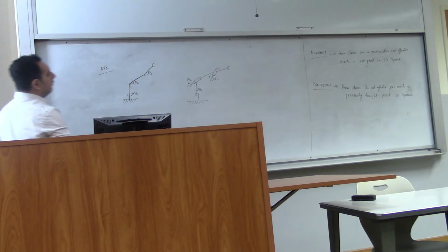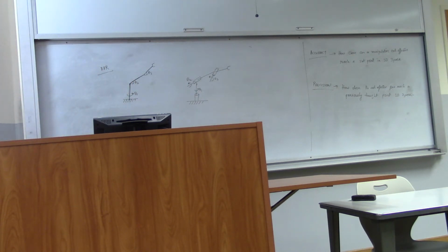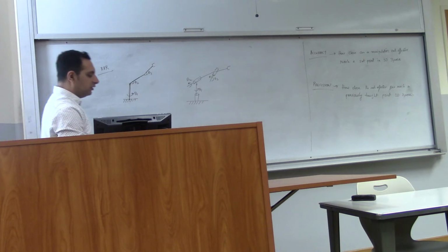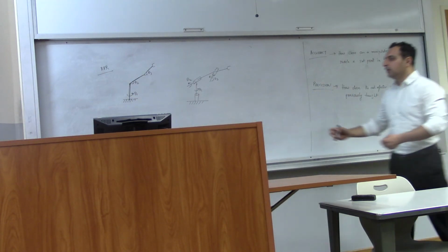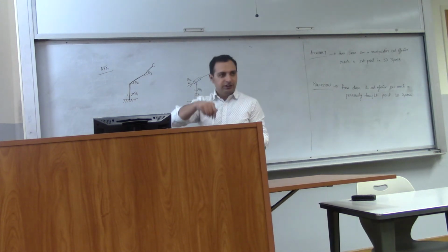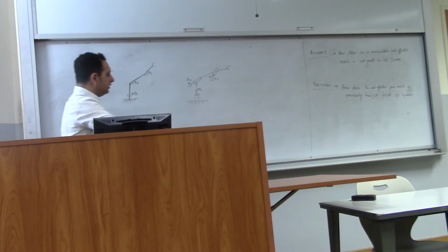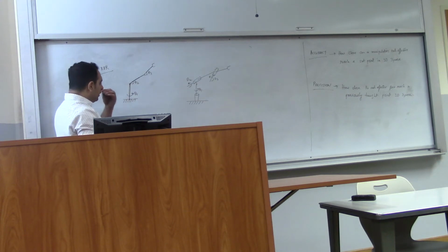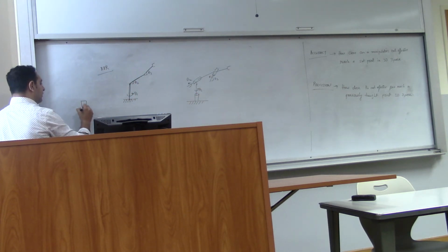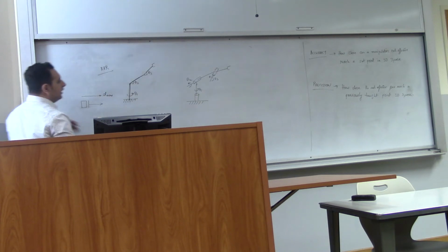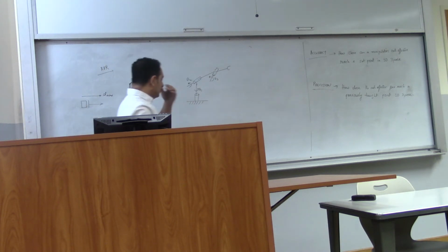Now, for a general case, if you're not given any limitations, you normally tend to assume that a revolute joint will have 360 degrees of motion. That means it can go around itself. But that's generally not true, because every joint will have limitations. Even a prismatic joint like this cannot extend to infinity, right? There is a certain maximum limit, d max, that it can go to. Similarly, even revolute joints have limitations.